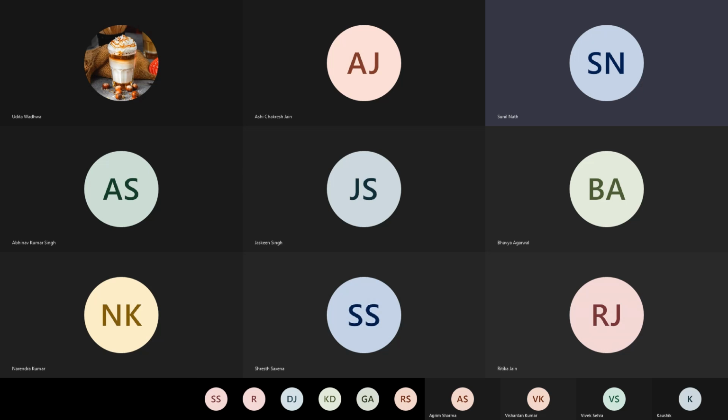So that's fine. Now I said you can heat the products to the final temperature. If you heat these products, for every product you would have n Cp naught for that product dT from 298 to T. That would be the sensible heat change. If I sigma over all the products, n integral 298 to final temperature T final in Cp dT, and I integrate that and sum them, that will give me the enthalpy change delta H naught products.